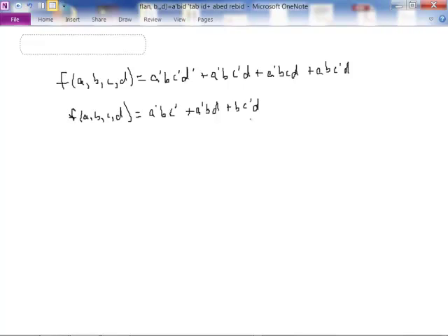This is a unique solution to the minterm problem, and so the size of the possible solutions is 1, right? There's only one solution with 9 literals in it that gives us the same output. So in this case, there would be no room to create additional constraints to put a watermark. But let's assume that we also had 2 don't care conditions as part of the design.